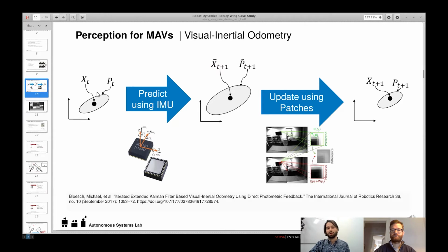In theory, as you might know, a standard Kalman filter with a linear model is guaranteed to give you the optimal solution for Gaussian noises and linear process models. So here the process model would be the prediction step. And of course, also linear observation models, which would be how we model the patches, how they influence the position. That's in theory. In practice, most noises are not so Gaussian. I mean, the one on the IMU, you could argue that this behaves similar to a Gaussian because it's kind of a natural noise, whereas the noise on the patches is for sure not Gaussian.